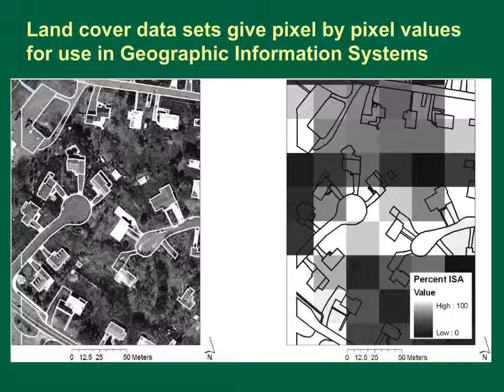This image also is useful for comparing the size of an NLCD pixel, which is about 30 meters on a side, or 900 square meters, to the size of a residential cul-de-sac. There are 2,878 such pixels per square mile of drainage area.